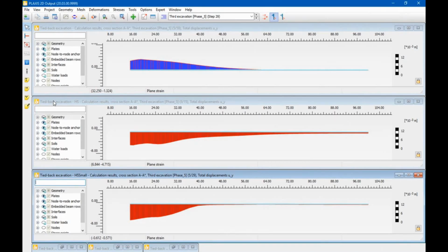Now, that would be very strange because, as I showed you, not in detail this time but at the beginning of the previous session, Mohr-Coulomb does predict that the wall moves inward, which is what we expect. So it moves slightly into the excavation. And then, of course, behind the wall new extra space forms, the soil fills up that space, and therefore you would expect the soil to settle. Nevertheless, Mohr-Coulomb says that the soil doesn't settle, the soil goes up. So that is the blue graph, that is soil moving upwards.